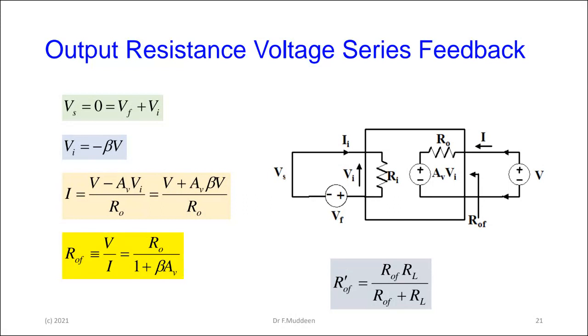Okay, and then if you just follow it now, right? So we've set the load, so we disable the current, and the circuit now becomes very easy. The feedback voltage, remember, is voltage series. So we know that the input voltage now is beta times the feedback voltage, right? We have no source to deal with. The current appearing at the output, we put a voltage on the output.